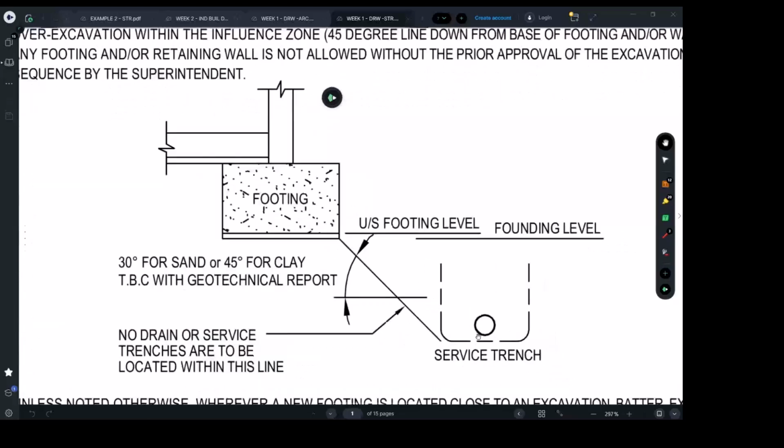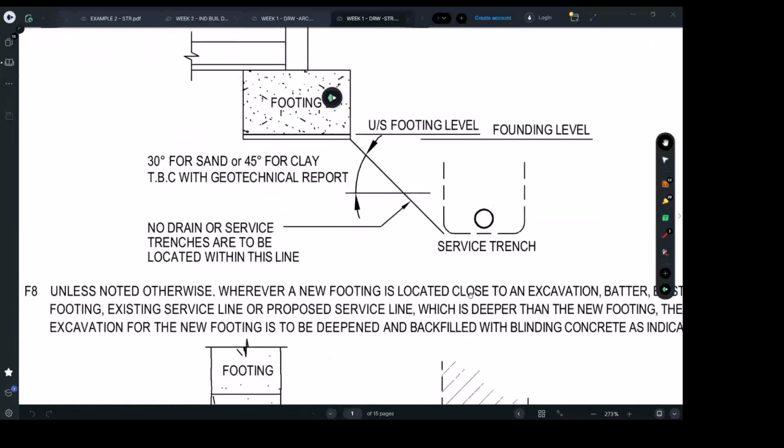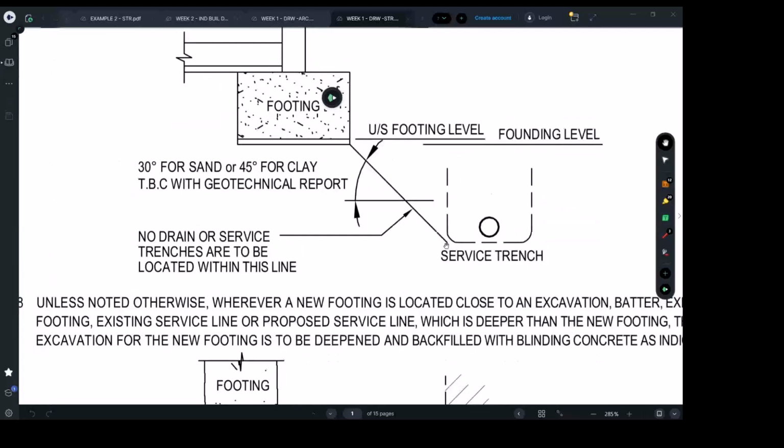You need to make sure that your footing is going to be away from the pipe, because number one, maybe this pipe will get damaged or leak, and the council or authorities want to come and fix it. When they dig next to your footing, it will be safe for the building and for them, right? Number two, you don't want to put pressure on the pipe. That's the protection we are required to look after, right?